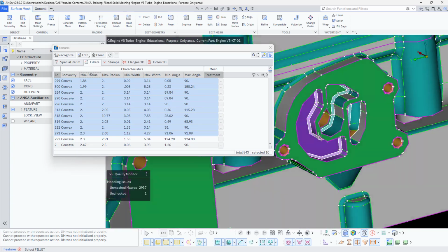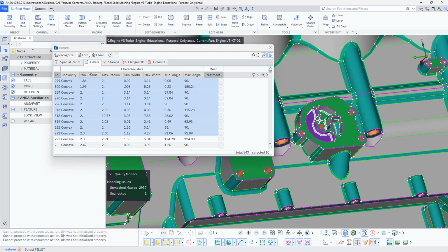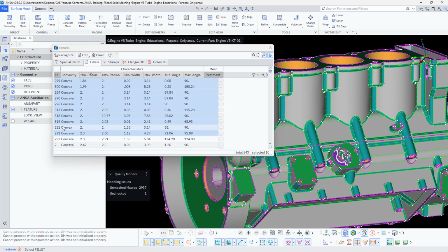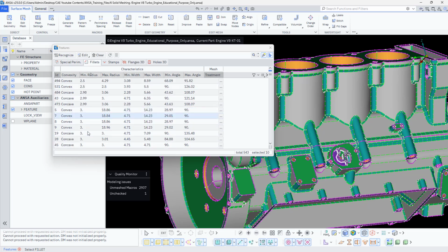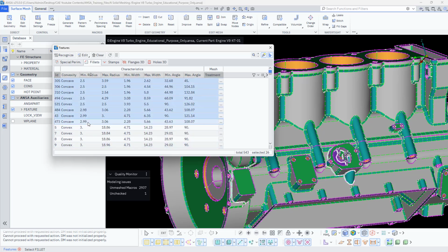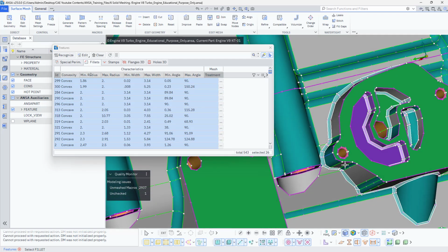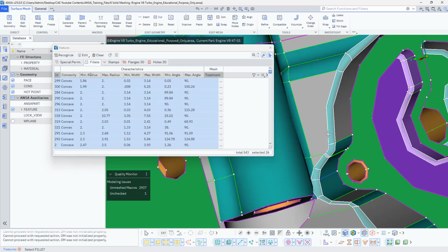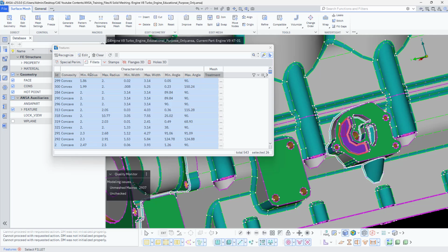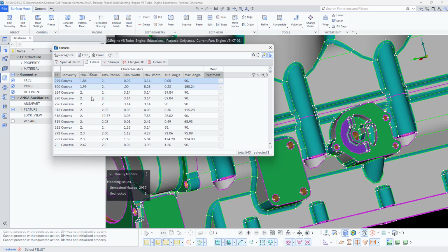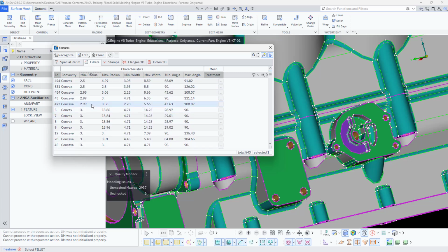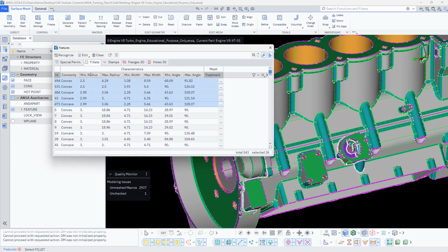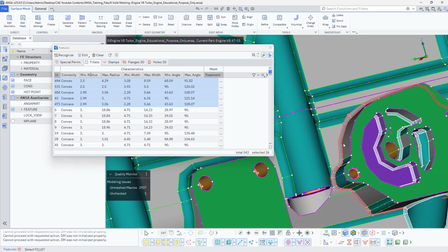and here is the view, right? And if you would like to go up to 3 mm, you can try. So let's say up to here. Let's show the radius regions up to 3 mm. Why I'm showing these is, sometimes let's say I'm going to mesh this model with a 5 mm mesh. So these regions might not be captured properly.